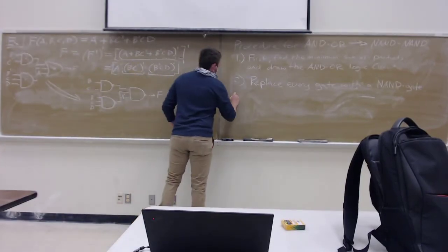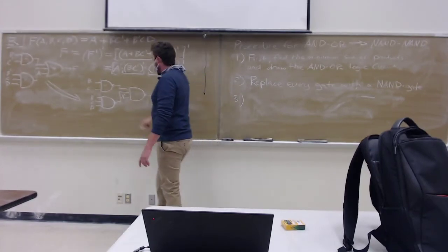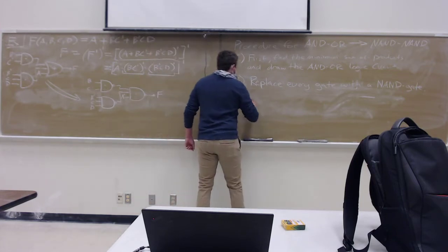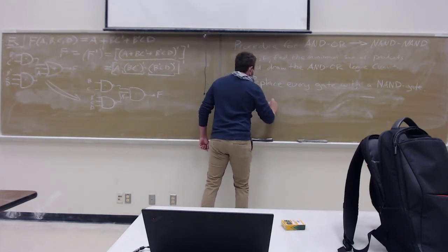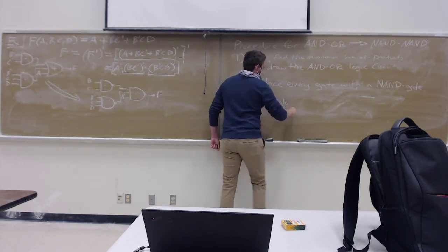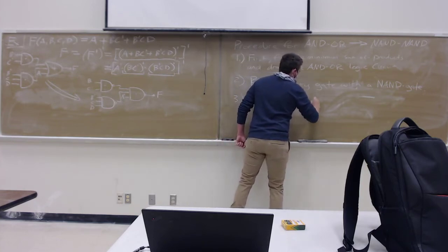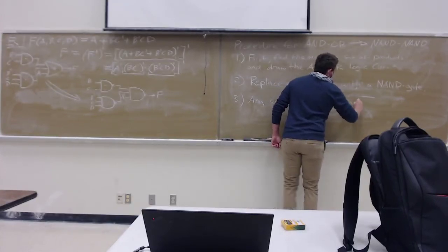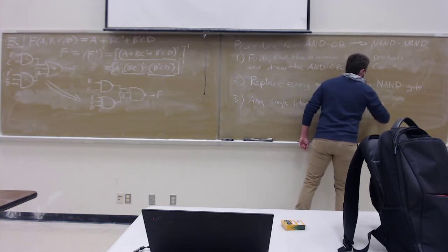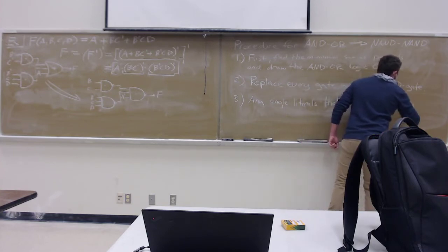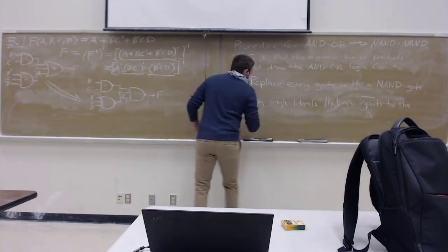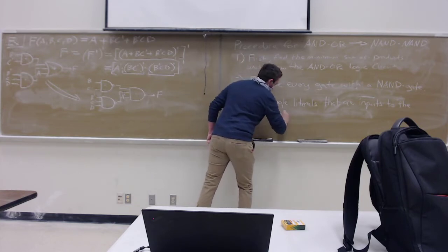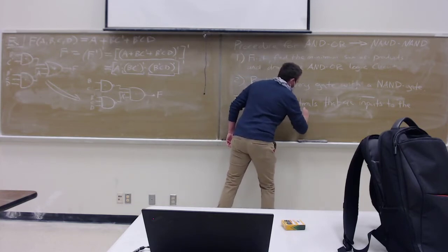Step 3, the last step, you noticed, was that we had to change A to A prime. So what that rule states is any single literals that are inputs to the output gate should be inverted.